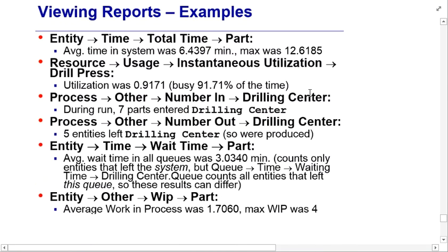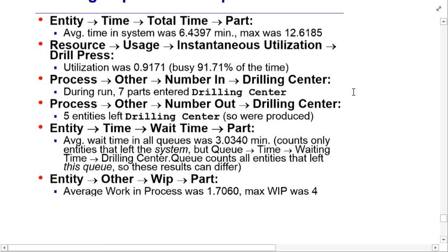And again, this is just going through some of the things you would look at: wait times, processing times. The other thing that's useful, especially in a manufacturing operation, is that you can assign whether something is value added or not value added. The example of that: moving things between 2 processes is not value added. Executing within a process, in other words drilling a hole, milling a part, molding a part, whatever it might be, is all value added. In other words, I'm increasing the value of the part. When the part is out of that operation, it's worth more than it went in. So that's a useful thing, especially on the manufacturing side.